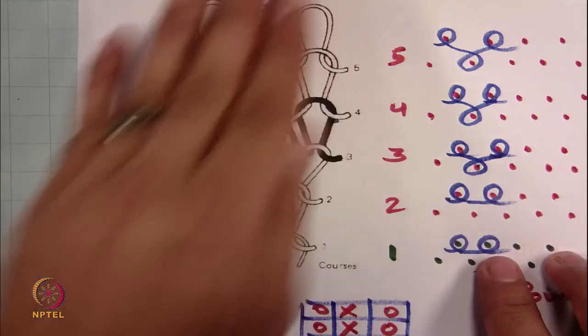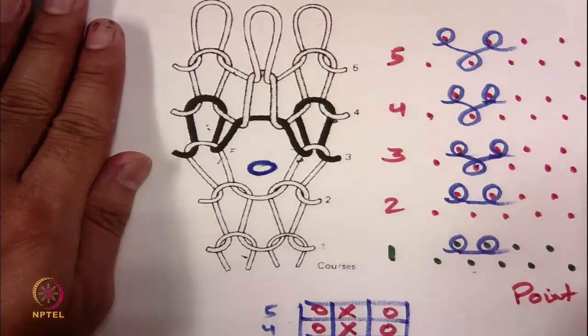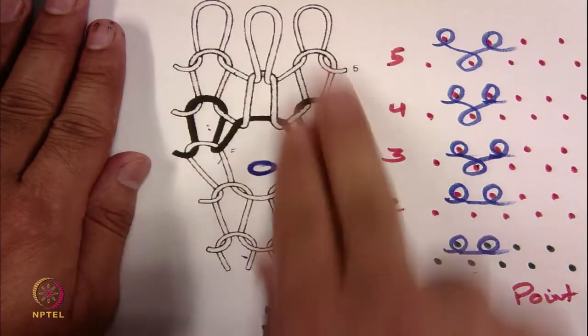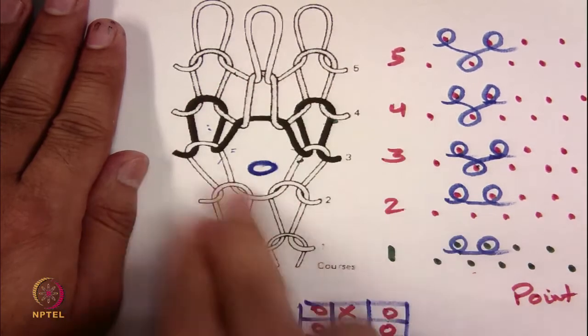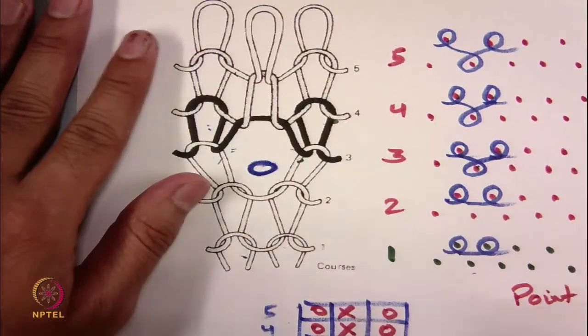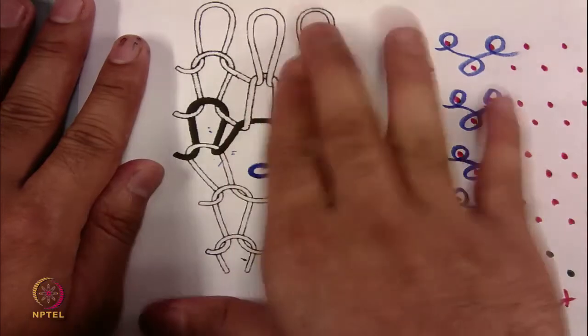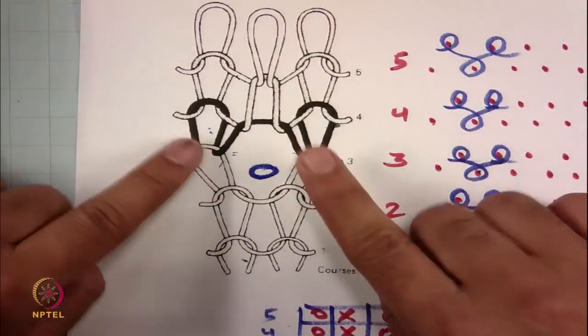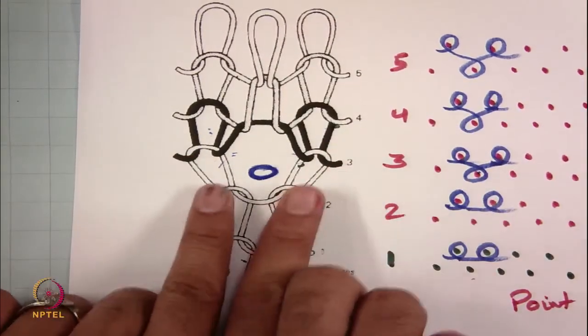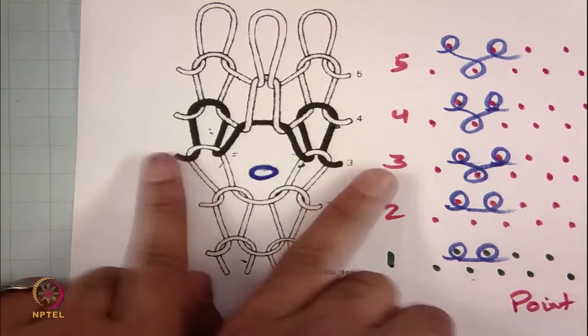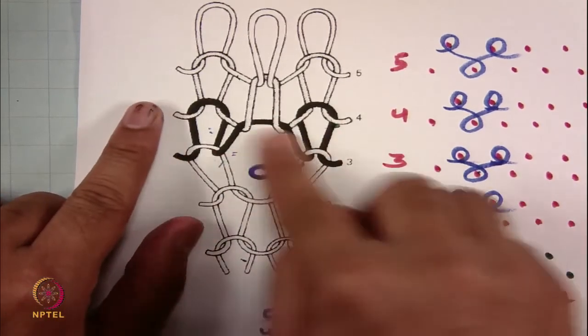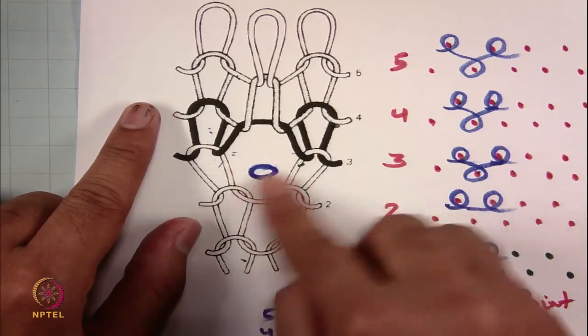But in reality when the fabric is formed, it will have a very complicated yarn path inside the structure. So this is how we represent this particular structure. If you carefully see, the moment I am engaging one front needle, these 2 loops are now opening up. Because of that a hole will be created inside the fabric structure.